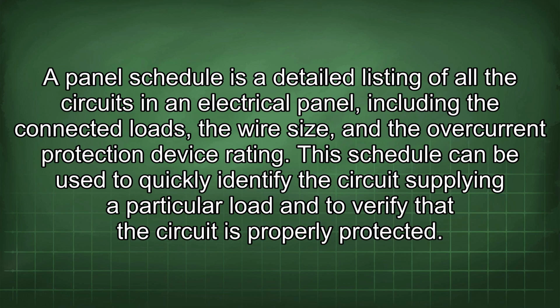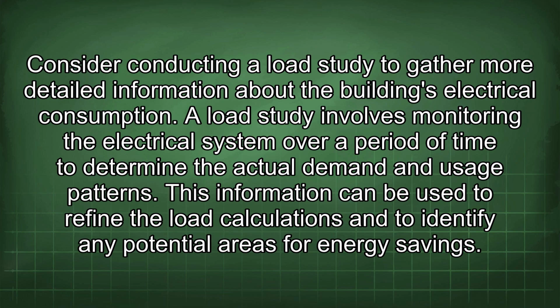Consider conducting a load study to gather more detailed information about the building's electrical consumption. A load study involves monitoring the electrical system over a period of time to determine the actual demand and usage patterns. This information can be used to refine the load calculations and to identify any potential areas for energy savings.